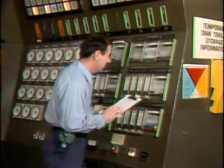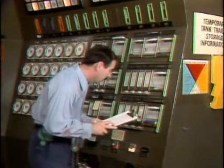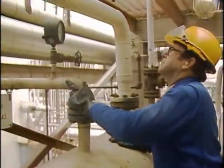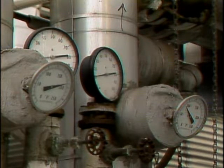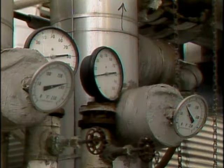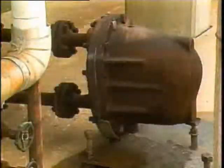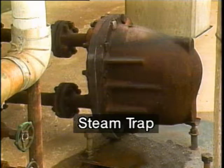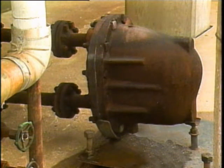Generally, an operator can observe instruments to determine if a heat exchanger is operating properly. These instruments are often located in the control room, but they may also be found on or near the heat exchanger. Depending on the heat exchanger and its use, pressure and temperature gauges may be placed on any or all of the heat exchanger's inlets and outlets. On heat exchangers that use steam, an auxiliary device called a steam trap is often used. The steam trap drains water, or condensate, from the steam in the heat exchanger without letting the steam escape. Lost steam reduces the efficiency of the heat exchanger.